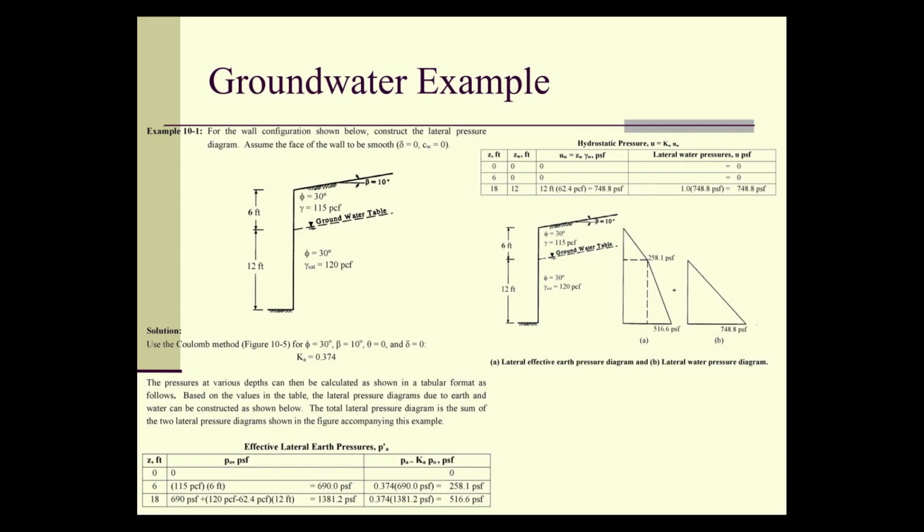Now, if you were to compute the resultants, my suggestion to you would be to do the following: compute the resultant force based on this triangle, and then compute the resultant force based on this triangle, and those results will be a third of the way from the bottom of each triangle, here and here, and then compute the resultant force of this rectangle, and the resultant force will be in the middle of that rectangle.